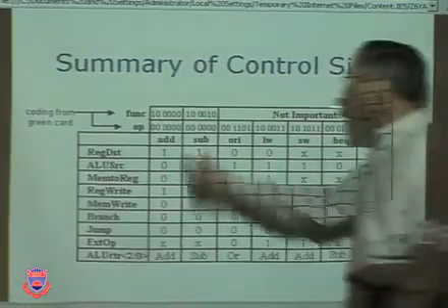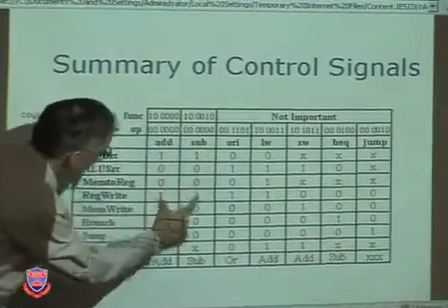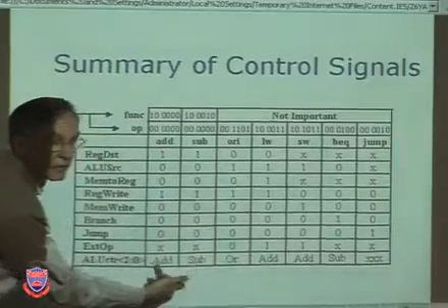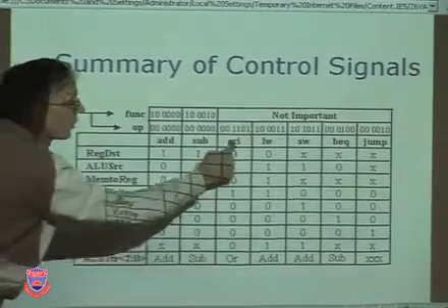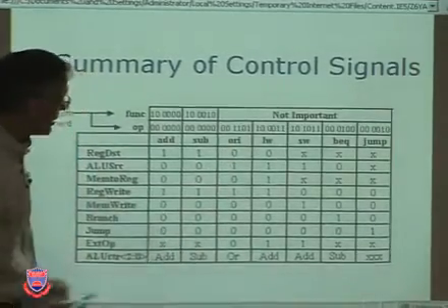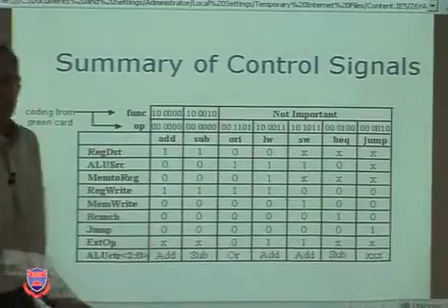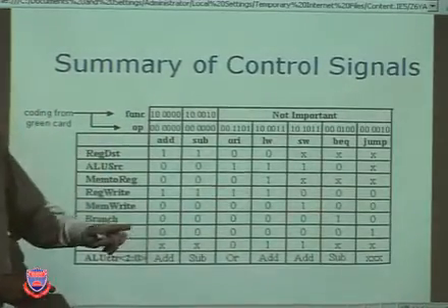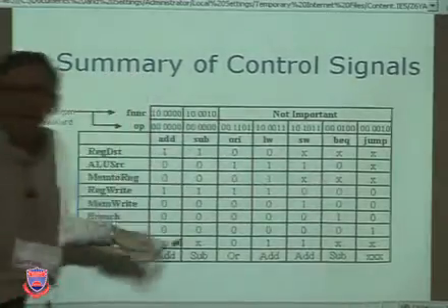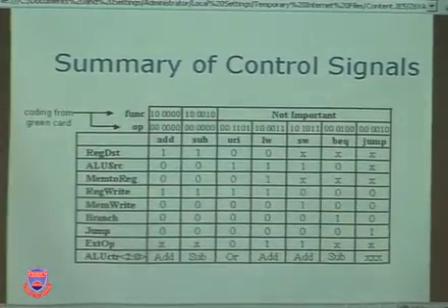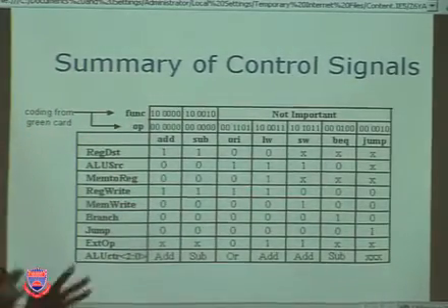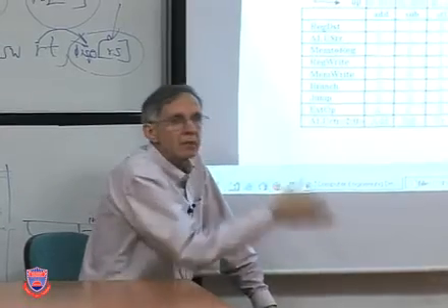Okay, for add and subtract, do you notice? Same all the way down the line except for the actual ALU operation. But for OR immediate, it's going to be a little different, isn't it? We need the OR here, that's true, but some of these are different because it's an immediate. So we're not taking 2 register operands. So as you can see here, this data in this table is simply a tabular compilation of all that we talked about in the last slides.